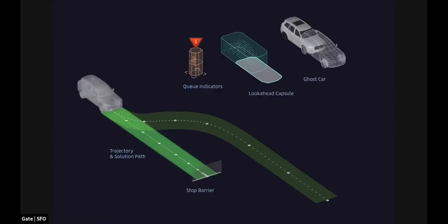A new can of worms, but something interesting here is we have this ghosted object, that we call look-ahead capsules, that we show where that object is expected to be at a future timestamp, and using those ghosted objects together with the planned trajectory of the vehicle, you're able to see whether that planned route is going to collide, for example, with some other vehicle.